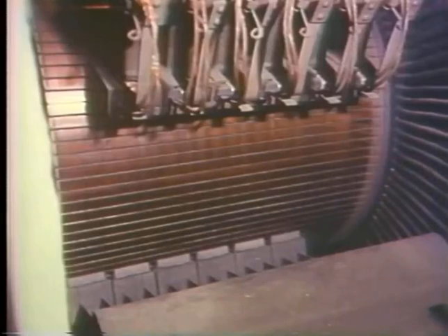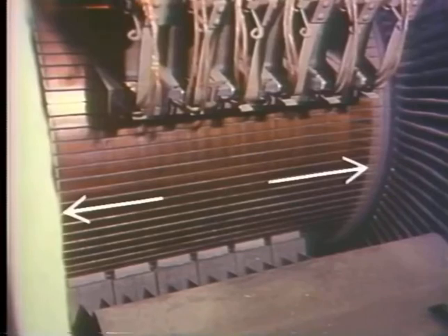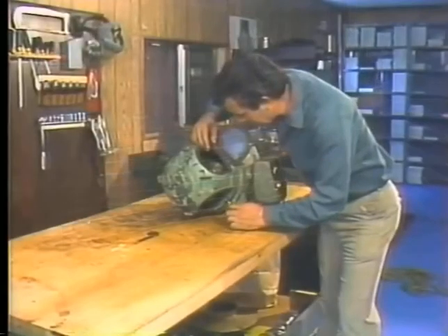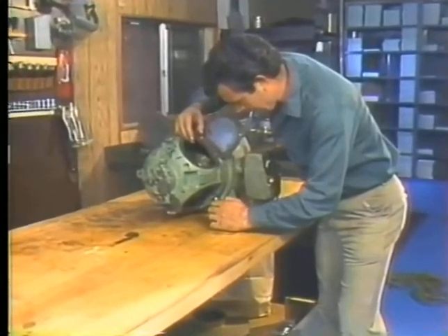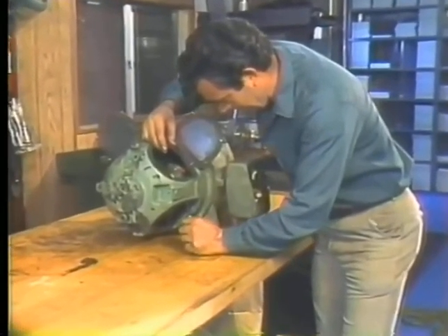The other thing you might have to do is adjust the stagger of the rigging so that the brushes cover almost the entire surface of the commutator. To do that, you loosen the brush holder bolts and move them so that the brushes cover as much area as possible. Make sure you always stagger the brushes in positive and negative pairs. Otherwise, negative brushes will track each other and wear unevenly. And by the way, those are general rules for staggering, but it's not always necessary to stagger the rigging on every motor. For instance, you don't stagger the brushes on a 2-pole motor.